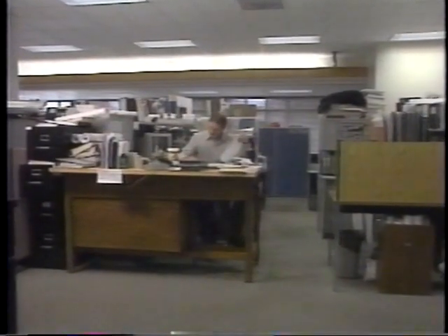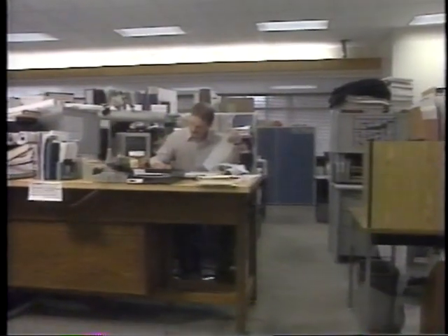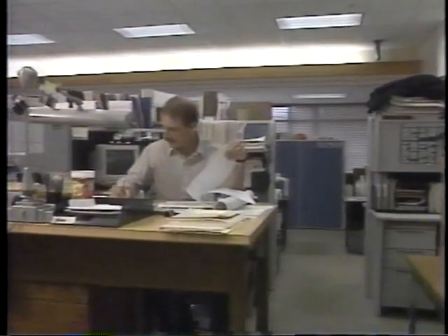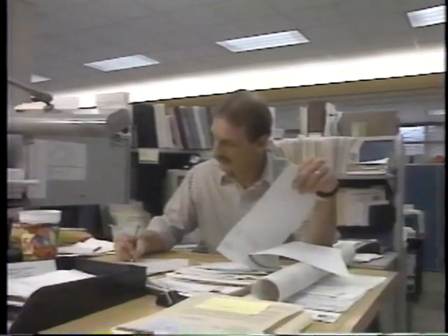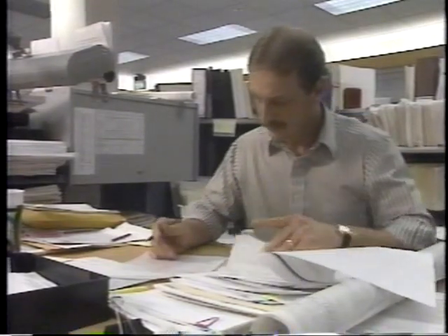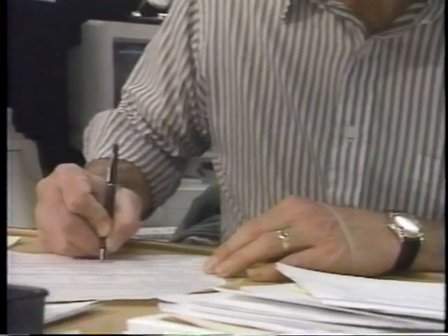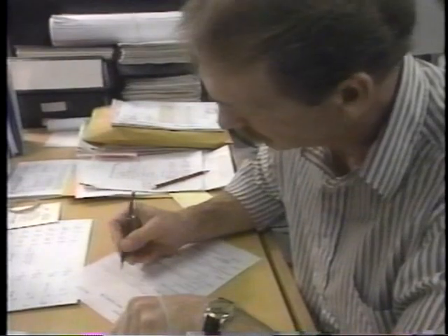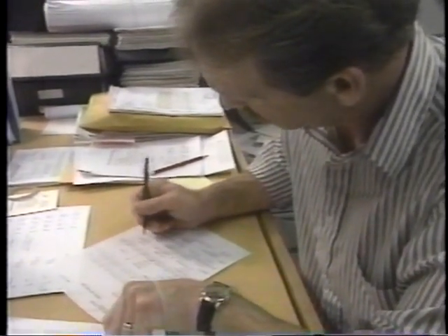The district should be alerted to potential overruns or underruns. Exception reports are submitted only when man-hour usage varies from contractor progress by more than a pre-selected percentage, such as plus or minus 15% on each contractor's operation and 10% on the contract total. Only those operations where an exception occurs need be shown on the report.